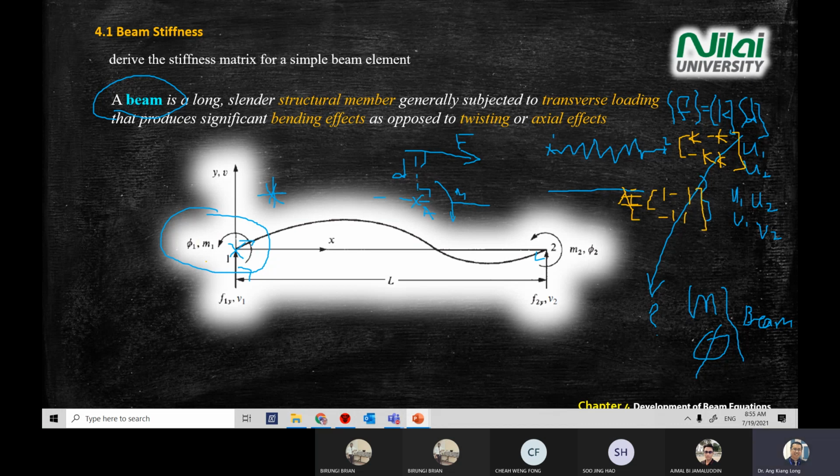Today we're going to do beam, which is a little bit different from these two, but the main difference is at the D component, the displacement component, in F equal to KD. In the D, you will see moment and twisting angle. So make yourself clear before we move forward to the next slides.